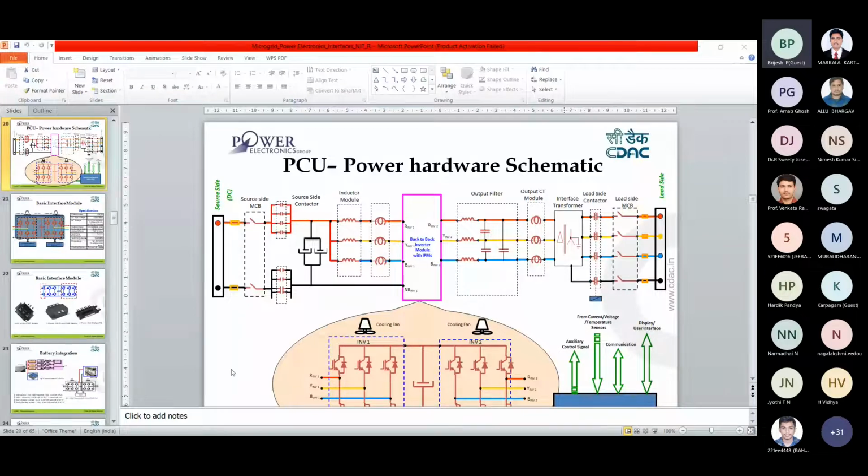This is the curve of the battery charging. Even with the battery VOC, you can identify the percentage of charge available in your battery. If you have a sufficient rest time before measurement, then from VOC itself you can identify the percentage of charge. This is the approximate VOC for a 12-volt battery and the percentage of charge available in your battery.